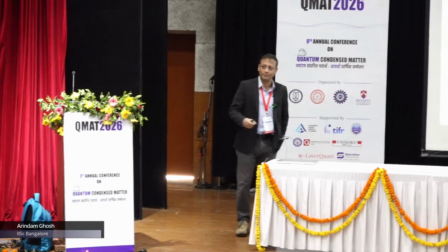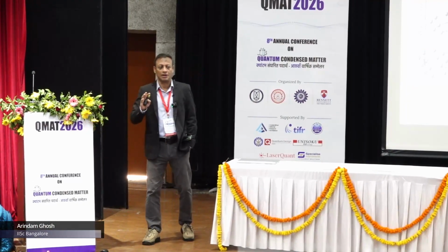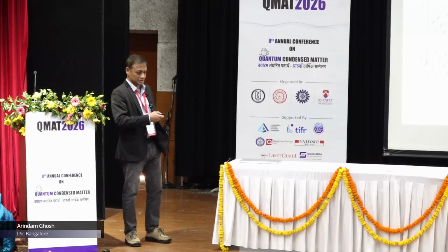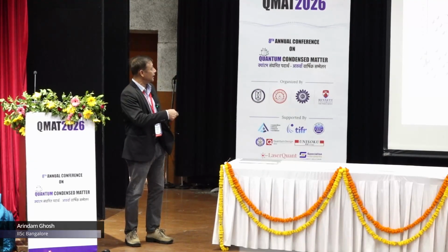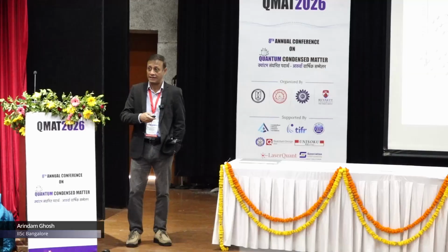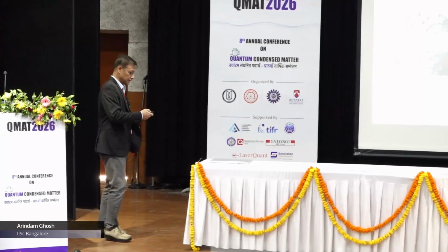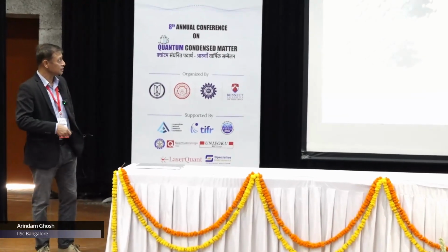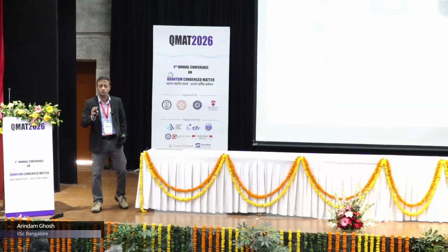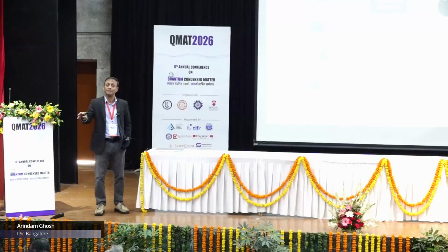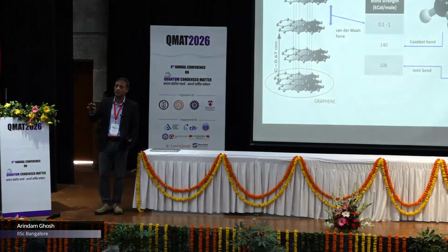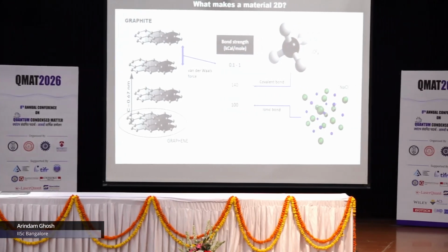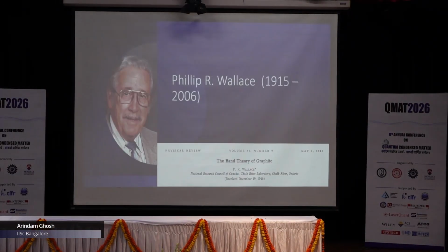So as far as what makes a material 2D is, as we understand, that it is essentially weak interlayer coupling, such as in graphite, and that is usually given because of its layered structure. Typically, the strength of the bonds, at least in vertical direction, in 2D is about 100 to 1,000 times weaker, which is why you can slip it out. 2D has been used as lubricant for decades. But now we can actually take out layers out and do science with it.